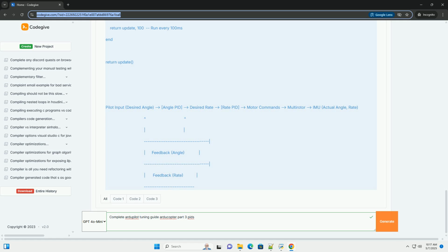3. Pre-tuning checklist, recap and emphasis. This is where many issues arise. Don't skip these steps. Vibration isolation, critical. Vibrations are the enemy of good PID control. Ensure your flight controller is properly isolated from the frame using soft mounts. Check your logs for excessive vibrations, or use the CLI test vibration. Aim for values below 30 for each axis, ideally much lower. Hard mounting or improper vibration damping will make tuning almost impossible.